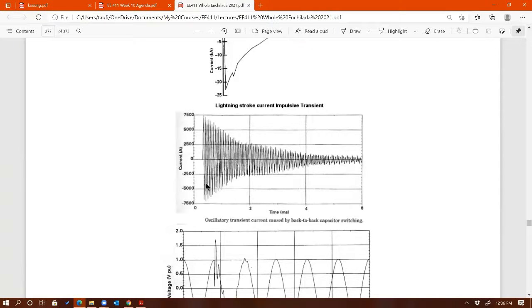And this is 60 hertz or 50 hertz, most likely 60 hertz waveform, right? It just squeezed together into, I don't know how many seconds. Oh, that's only 6 milliseconds. So sorry, no, this is the high frequency oscillation on the 60 hertz system, right? So you can see that's current. So the amperage fluctuates, right? From big fluctuations and decays, right?